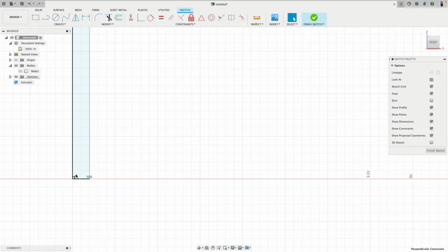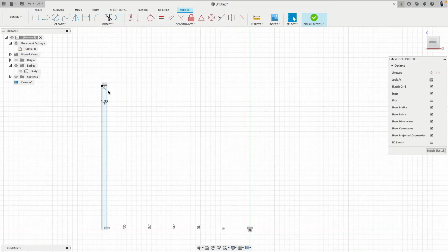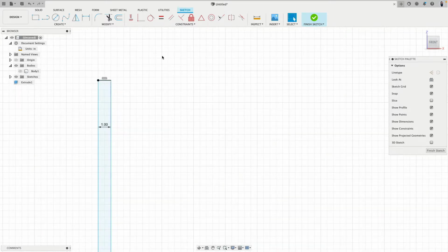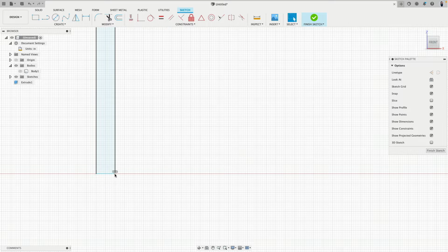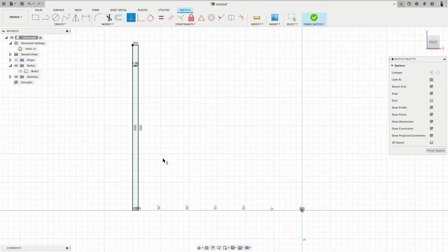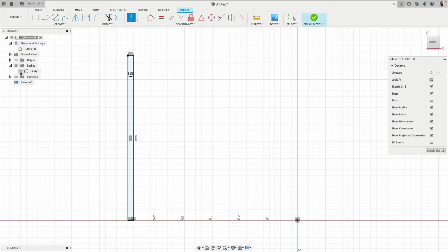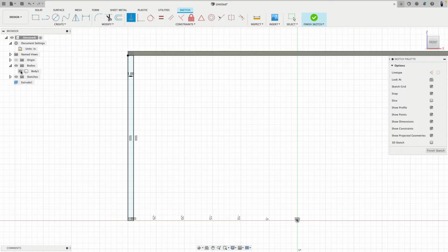This is now the perfect height. This perpendicular constraint I remove because here I will put in my vertical constraints by hand. Now this is blue. Why is this blue? I see this can actually rotate. So horizontal constraint. Now it's black. Very good. Okay, so this is now the 1 inch